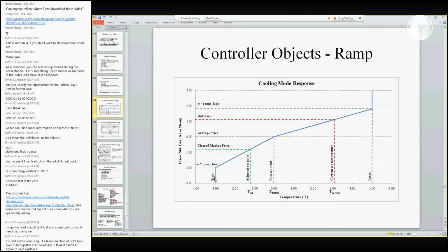And then we have, of course, our limitations to say that customers can say, well, I'll let you take 5 degrees of my thermostat, up to a certain point, and then I'm just done, and vice versa. You can pre-cool me a little bit. I'll be quite honest, we don't use the preheating and pre-cooling modes that often. We found that they're pretty inefficient, and it's hard, at least in a residential unit, to accurately predict when you should be using it.